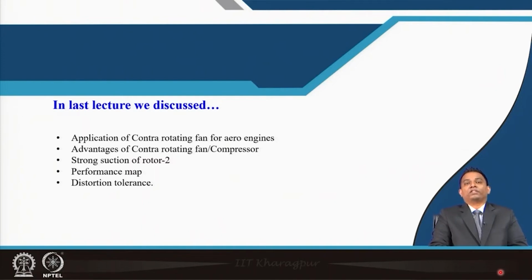And that's what has attracted attention, because we are moving towards wide body aircraft. Under that condition, the flow entering my engine will have inflow distortion because of inflow boundary layer development. That will deteriorate the performance of my engine. So people are looking for special applications or special kinds of designs where they can avoid or minimize the effect of this distortion.